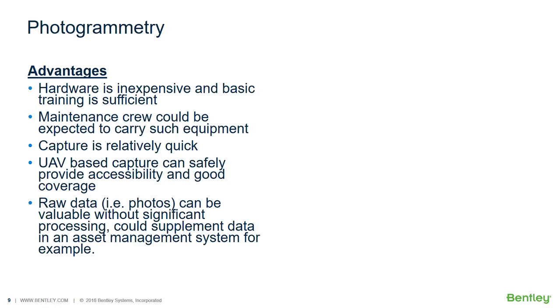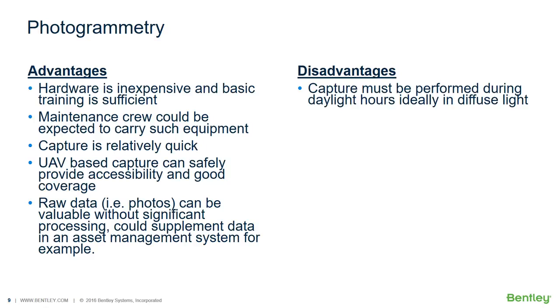Now, we were talking about photogrammetry advantages. We also need to cover the disadvantages. Capture must be performed during daylight hours, ideally in a diffused light. So you don't want to use flash. You want a nice bright scene.